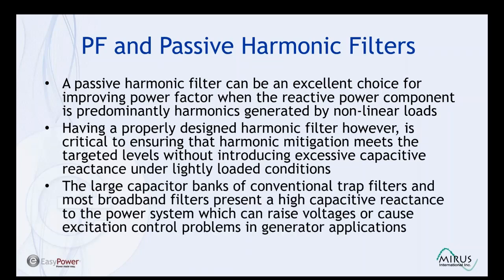The large capacitor banks of conventional trap filters and most broadband filters present a high capacitive reactance to the power system, which can raise voltages or cause excitation control problems with generators, and also shows up as very low power factor over a wider load range on the filter.